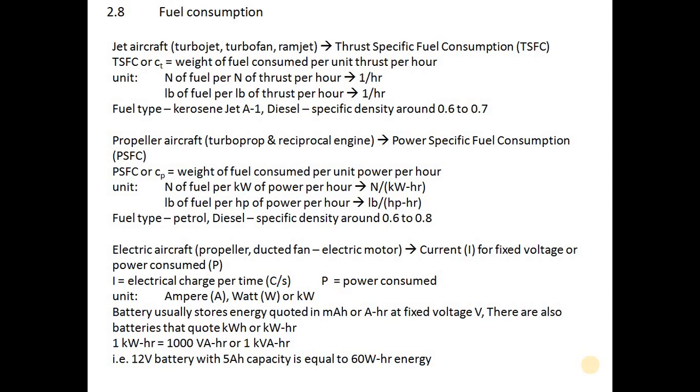The fuel consumption is measured as thrust-specific fuel consumption, or TSFC. Sometimes people write it as TSFC or simply C or C subscript T. T referred to the thrust. The definition is that it is the weight of fuel consumed per unit thrust per hour.